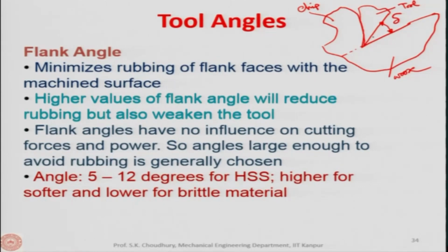So, when the tool actually removes chip material, the flank face rubs against the already machined surface. Therefore, we have to have the flank angle to clear the flank face from being rubbed over the already machined surface. So the flank angle is also called the clearance angle, because we need to clear the flank face from the already machined surface.